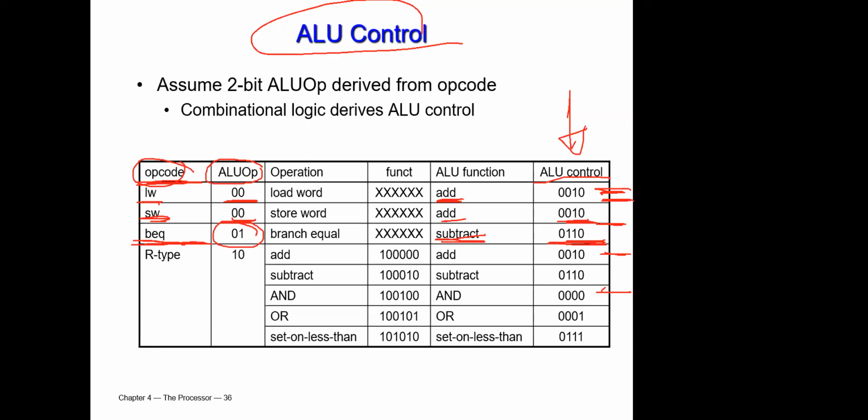The issue actually will come if that opcode is R-type. Because if the opcode is R-type, meaning that the opcode is all zeros, I now know that it is an R-type, but I don't know which function. In order to know which function, I have to decode my function value, which is located at the last 6 bits of my instruction.